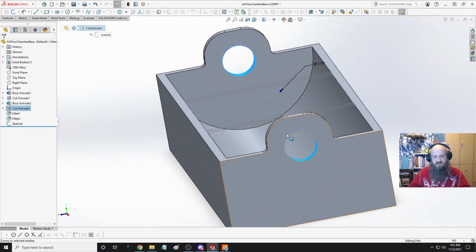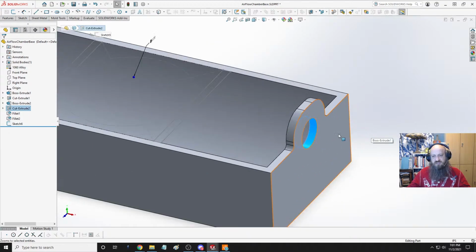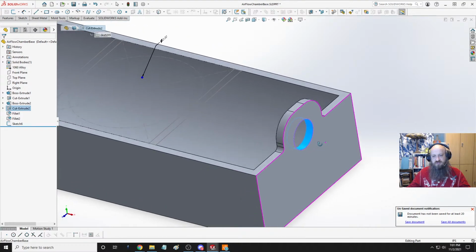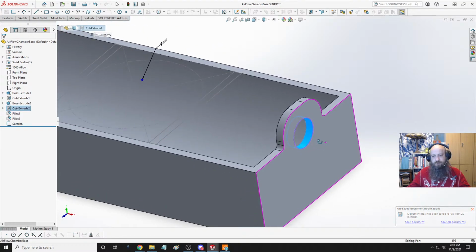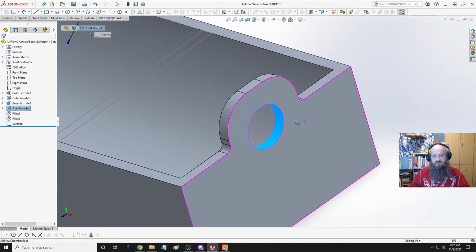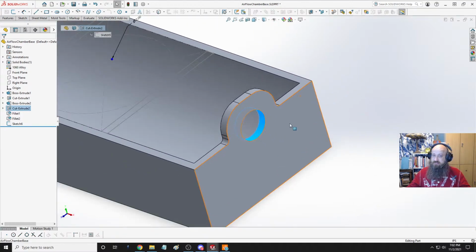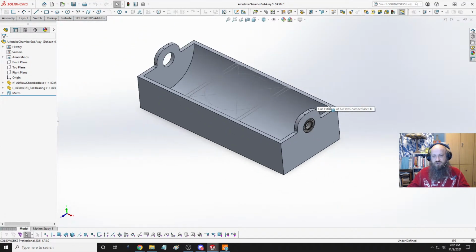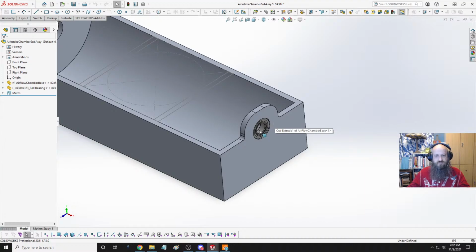I might change this to where it actually is 1/2, and it just sandwiches together and bolts so it encompasses the bearing. Which means it wouldn't have to be a press fit. It could just be a clamped-in fit, if that would work. Alright. Definitely some modifications coming in the future, that's for sure.